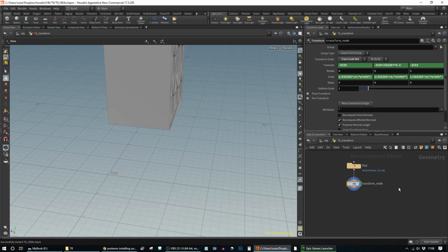There are two kinds of Houdini digital asset you can create. First of all, there are assets that simply consist of a number of network nodes, which can be extremely complicated and include lots of nested nodes. But you would typically use this inside a network, inside Houdini. So if you have a collection of nodes that you use very often, you could package these up and just use the digital asset rather than having to rebuild them every time.